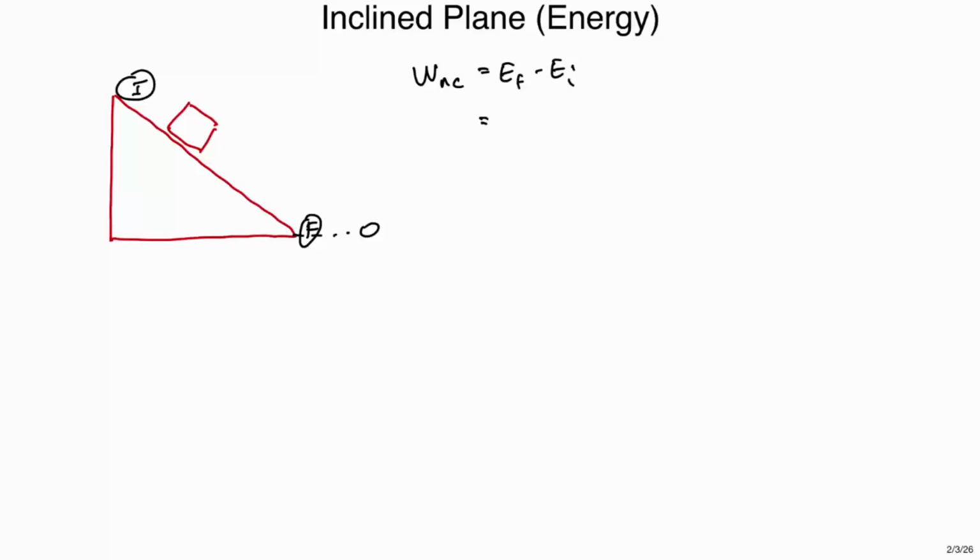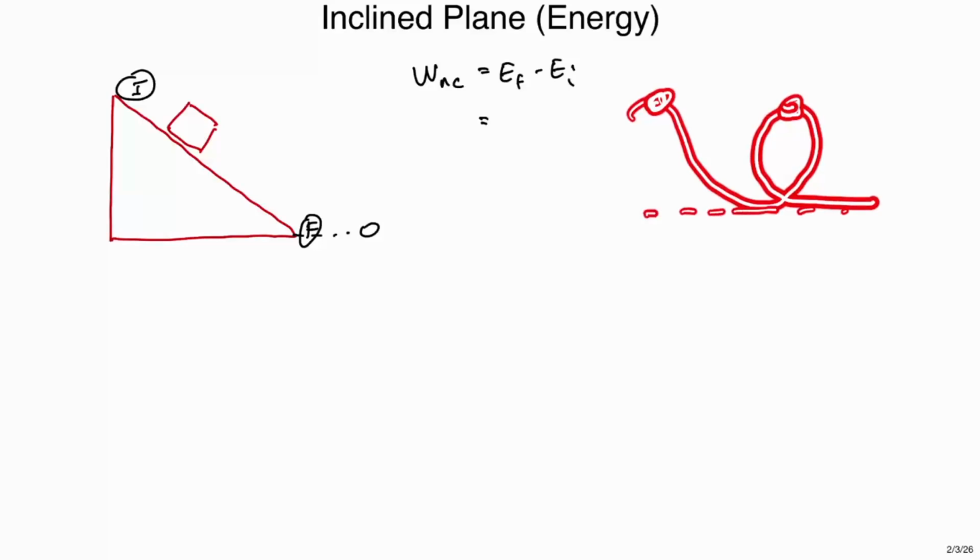The other thing you're going to put is 0. What I do for safety, and because my brain doesn't like thinking about negative work, I like to put 0 at the lowest point in the problem. This is not necessarily the same as your final position. In this problem, it is. I just put 0 at the lowest point the object makes. So like if it were a roller coaster and the object were doing a loop-de-loop like that, right? And I'm just comparing where it started with the top of the loop-de-loop, I'd still put 0 down here. That's just me, right? That's how I do it.